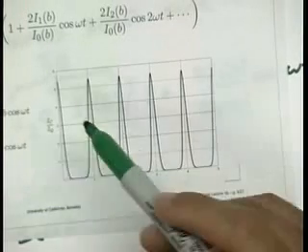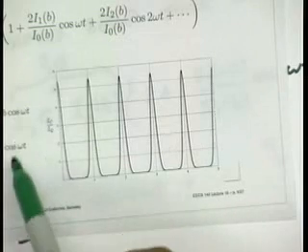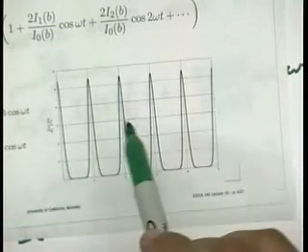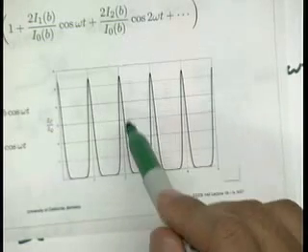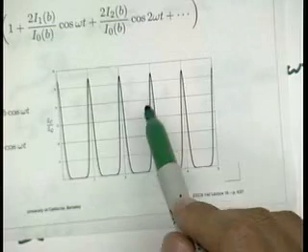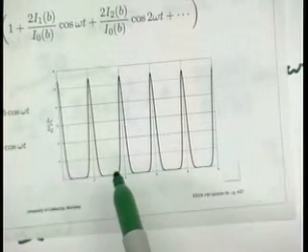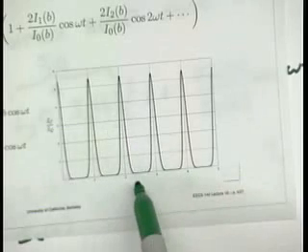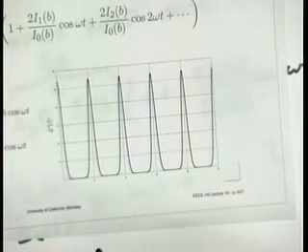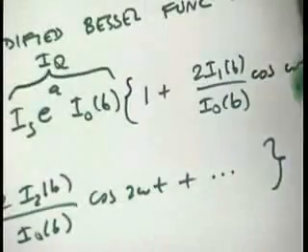I didn't. But what's interesting is you see that the collector current waveform, even though the input is sinusoidal, has this very peaky response. When it's positive, the current shoots up, right? This is IC divided by IQ. So you can see that the collector current is 5 times larger than its bias, which is at 1. And then when the VBE goes negative, the current essentially goes to 0. The device shuts off. So as a function of B, I can plot this a little more carefully.